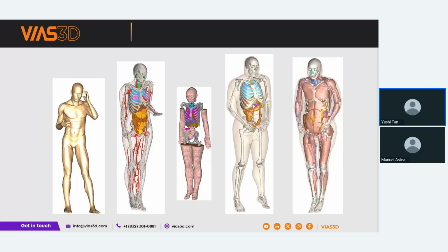All right. So in terms of biomodels, the level of detail of these models depends on the application itself. For example, for SAR calculations, maybe all you need is just a homogeneous phantom model to mimic the certification test. And since the material definition is homogeneous, you can get the results pretty quickly, to get a ballpark figure. Now, if you need the full detail, you can get a more sophisticated model in your simulation, for example, a voxel model. Typically, these models can be quite detailed. Most of the models you're able to get down to, let's say, 1 millimeter resolution. And most of them offer multiple resolutions depending on what you need in terms of, let's say, the certification.